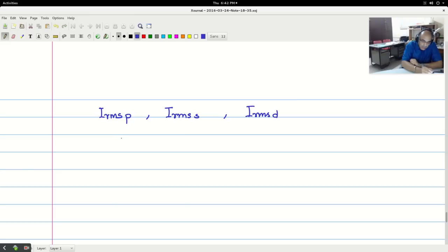there is another new term that I am going to introduce called J. You may or may not have used it. J is called the current density. For different materials like copper, aluminum, there is a particular current density that is allowed as a standard. It's an international standard. This is generally in terms of amps per square millimeter.